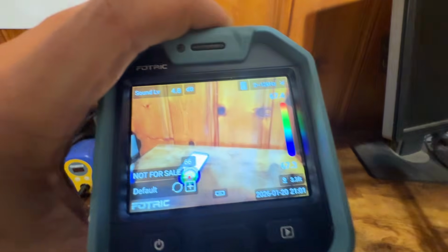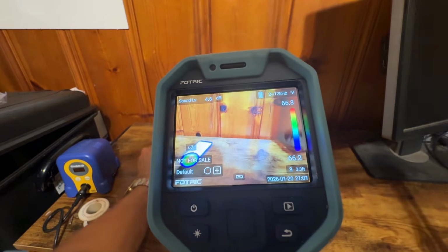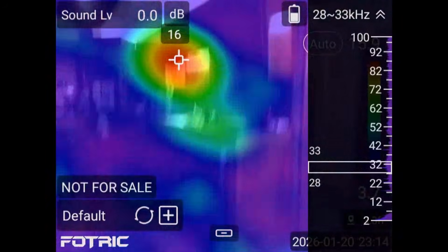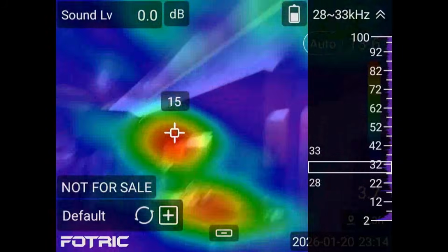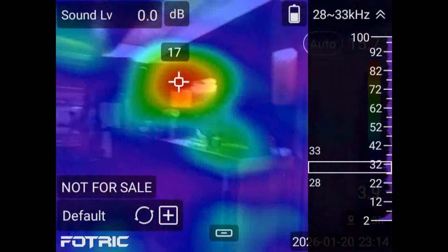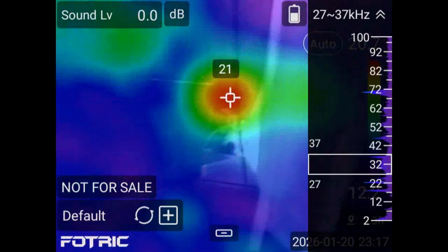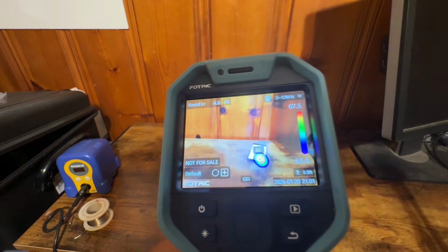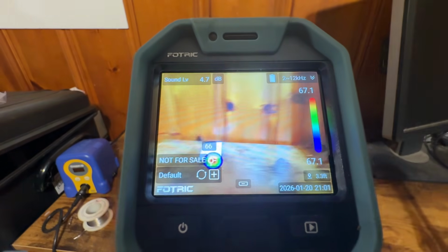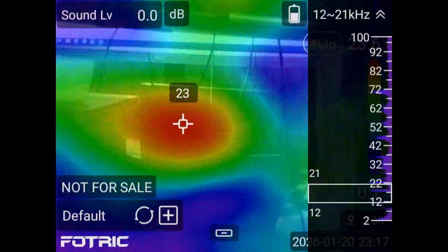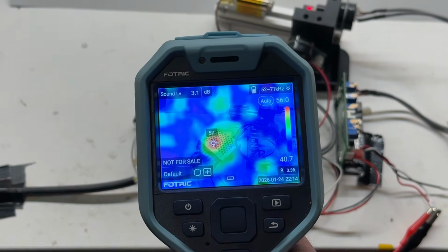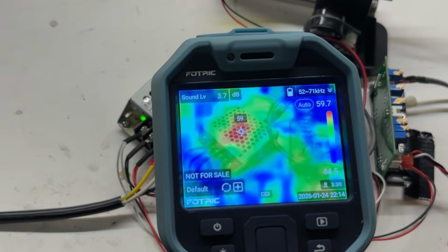An acoustic camera takes pictures and videos of sound in much the way that a normal camera takes pictures of light, or a thermal camera takes pictures of heat. It shows you where the sounds are coming from. So, like the cricket there, you can find the source of noises accurately, whether it's something silly like a cricket, or more industrial uses like air leaks, machinery vibrations, or even something like tracking down a winding inductor or in a switching converter, or piezo effect noise from a capacitor.